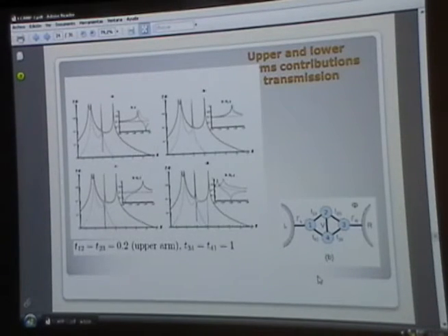This Fano effect is this kind of peaks where you see the transmission as a function of the energy: some peaks go to 1 fast, and even faster go to 0 or to a very low value. So you have a resonance and anti-resonance very close to each other. That is the Fano effect in a device like this.